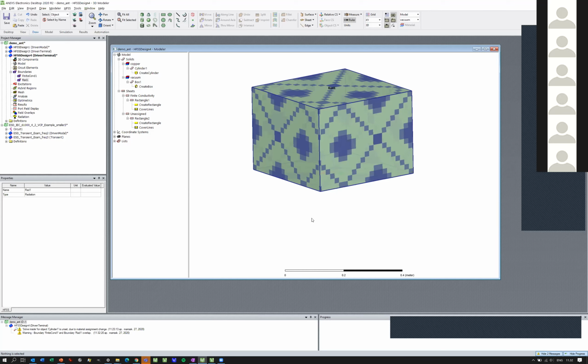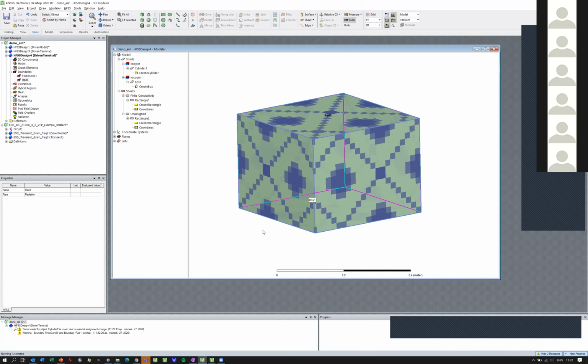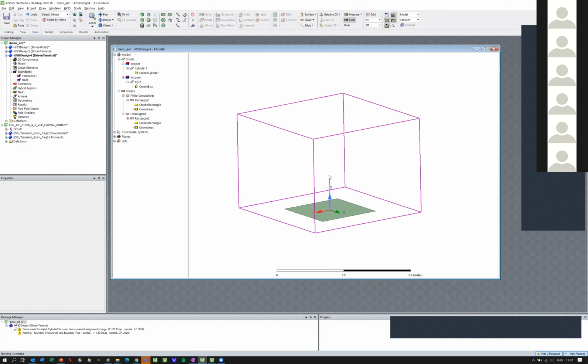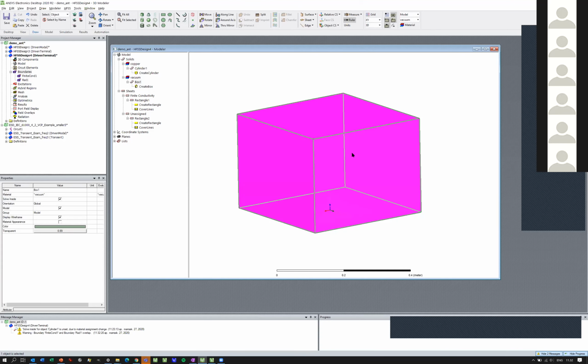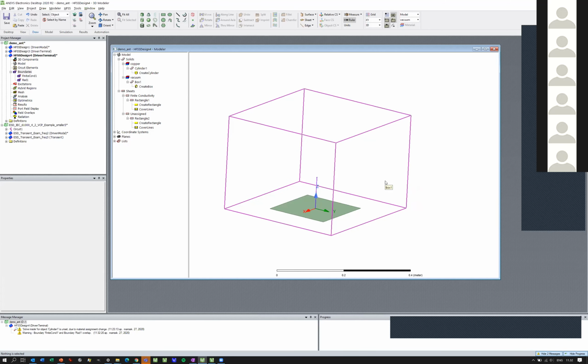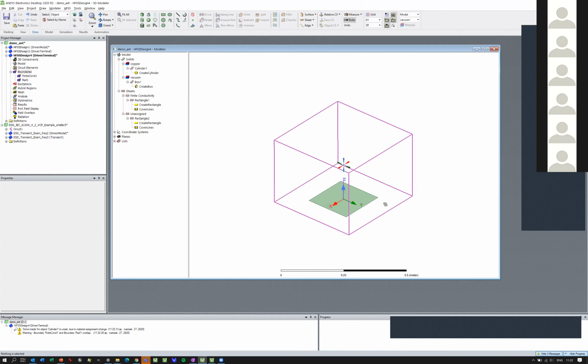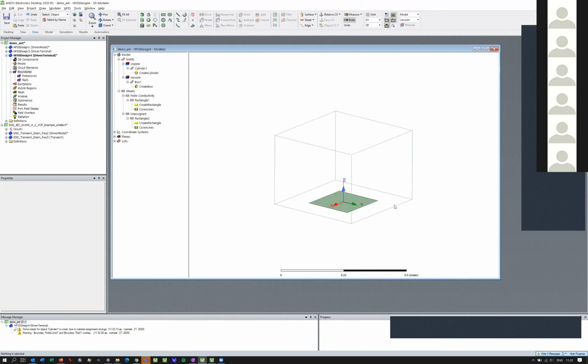You can see those triangle absorbers on a wall. So this is my absorber. It will kind of eat all the electromagnetic waves which are radiated by the antenna, and nothing comes out of this box. So this is kind of blocking the radio signal and measuring at the same time, measuring how much energy comes in which direction. So this is my boundary conditions.